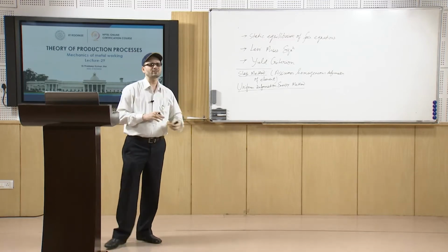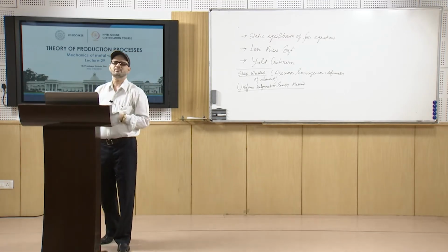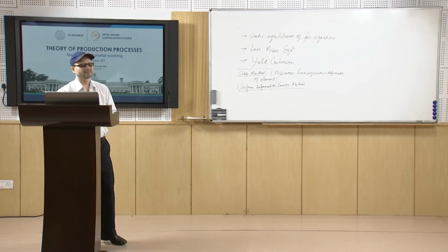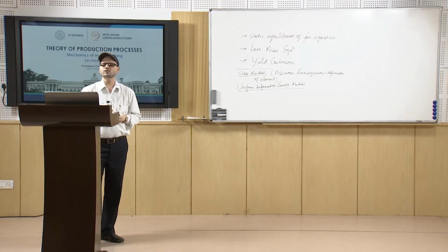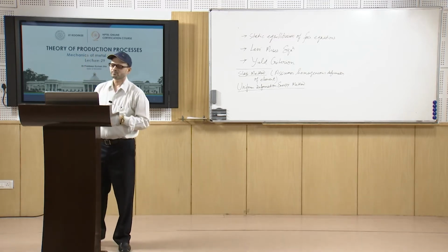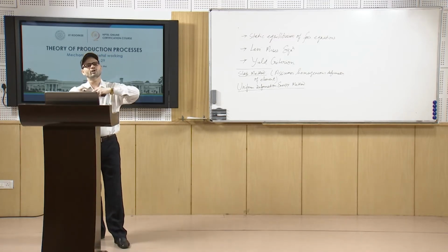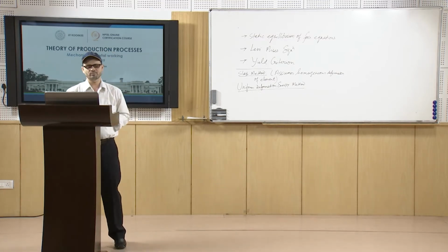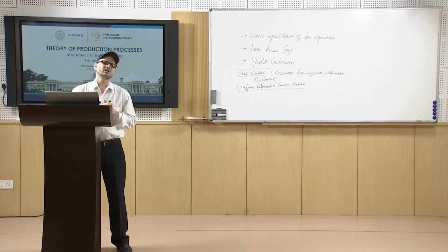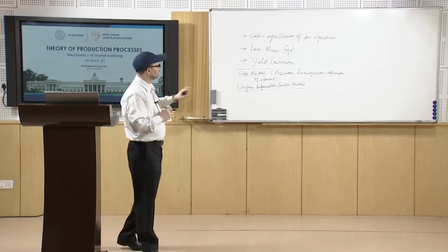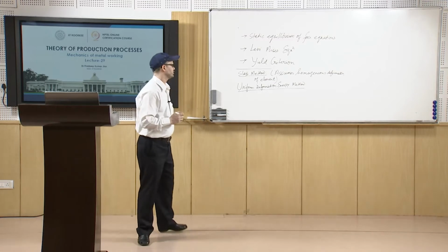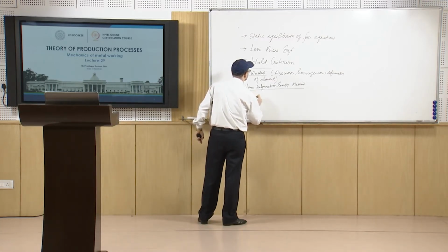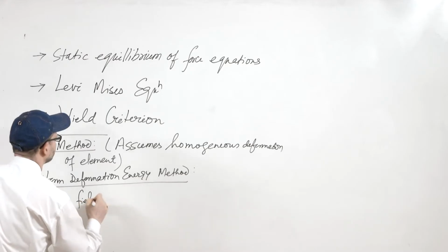On that concept, this uniform deformation energy method is used. Third is the slip line field theory, which permits point to point calculation of stress for plane strain conditions. In the slip line field theory we do that analysis.